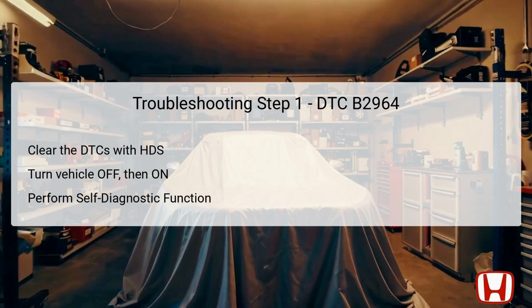Next, perform the self-diagnostic function with the HDS for the climate control unit. This process checks the operational status of the climate control system and can often reveal any persistent issues that could have led to the previous DTC. Following these actions should lead to either a confirmation of the issue or provide a clean slate for further diagnostics.